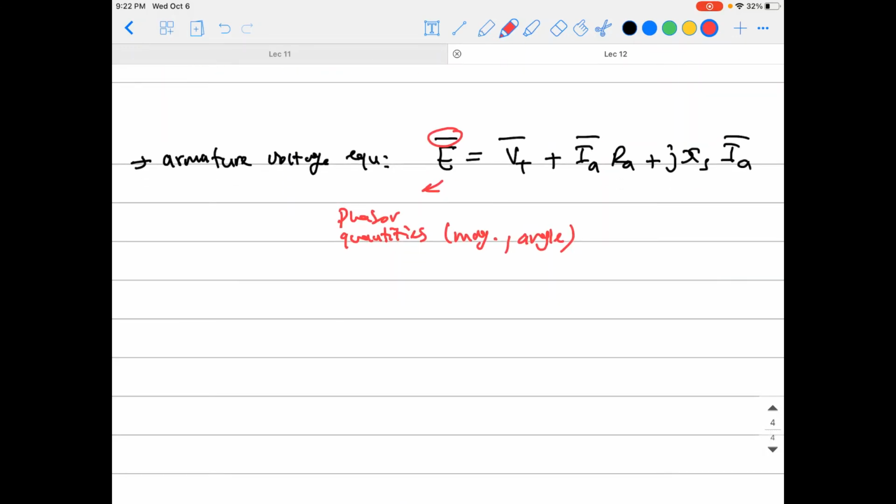And just to keep you informed, again, the terminal voltage here, V terminal, okay? And I'm going to have those two marks, that means the magnitude. And if you want just the magnitude, so you get rid of the upper dash here and just say V terminal, that means you are meaning the magnitude of this thing. For this equivalent circuit, that will be a phase quantity, like I said, because everything in this equivalent circuit is per phase. Okay? Usually it is given in line-to-line form in the machine information, because that's the typical way we deal in the public grid. Okay?